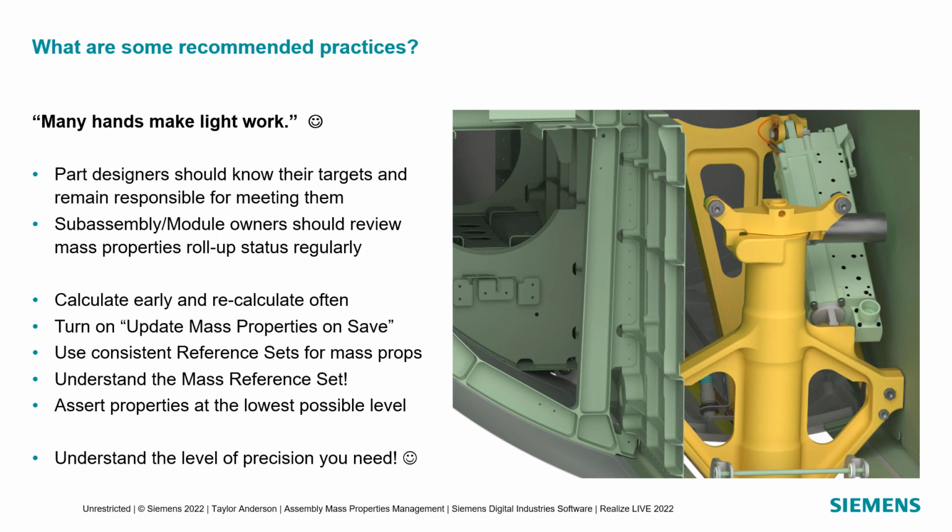There's a distinct usage of that reference set for mass properties, right? And this is more of a site setting where you're going to be looking to the contents of a particular reference set for calculating mass properties, regardless of what's displayed at the moment, right? So a little distinct usage there. Showing and hiding things in the display should not be changing the mass properties, we think, and customers have agreed. So that's a little important thing to understand relative to mass properties. And again, those two distinct usages.